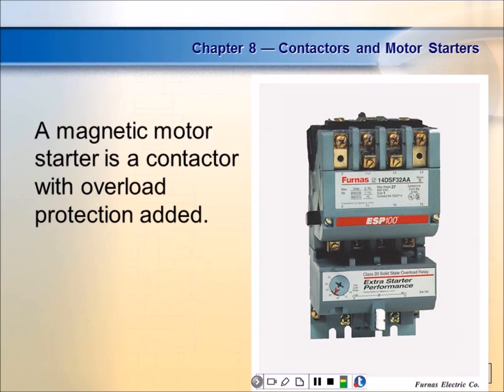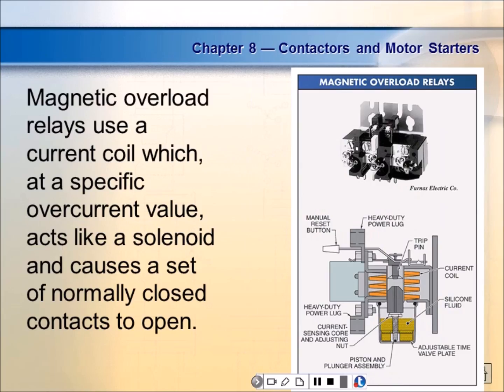This is a motor starter with electronic overloads on it. Now, of course, the advantage of electronic overloads is usually they are adjustable, right? So you can actually adjust them here. The biggest disadvantage of electronic overloads is they cost more per overload. So what you'll find out on new installations, you'll probably see a lot of electronic overloads. On installations that are 2 or 3 years old or older, you're going to see heater overloads. Everybody okay there?